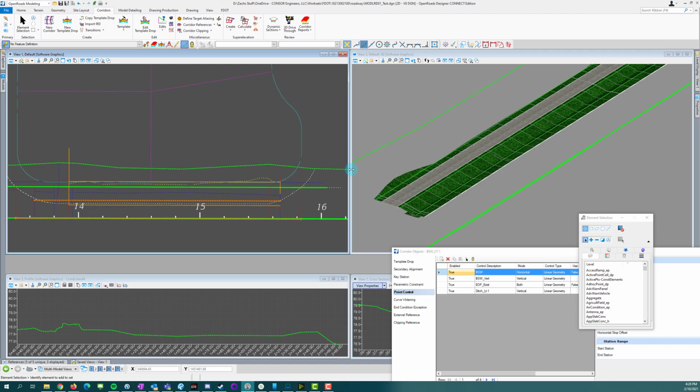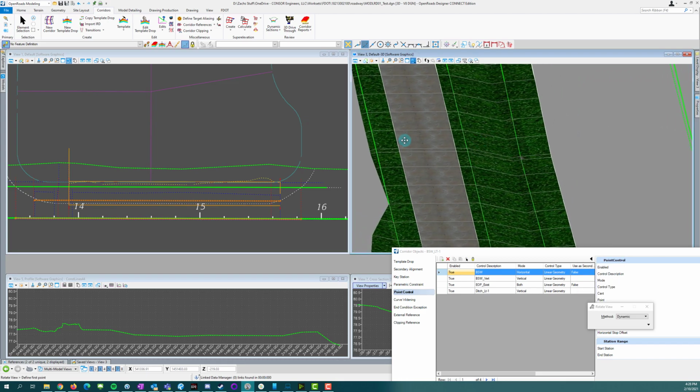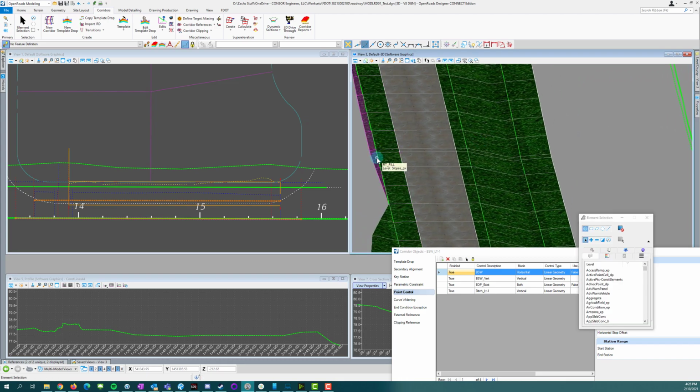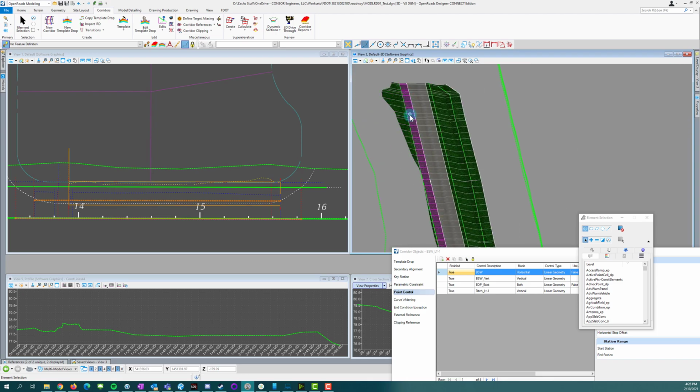So those are some things that you can go back, and this is part of the iterative process where you're going to kind of go back and start adding some more points and adjusting this profile so that you don't want to be trapping water back here. So you can see we're a little bit trapping water here. And more than likely, I think we're going to be okay here. We could potentially reduce this down to 1 foot and this to like 1 on 3 or something like that to get this to tie within the right of way.